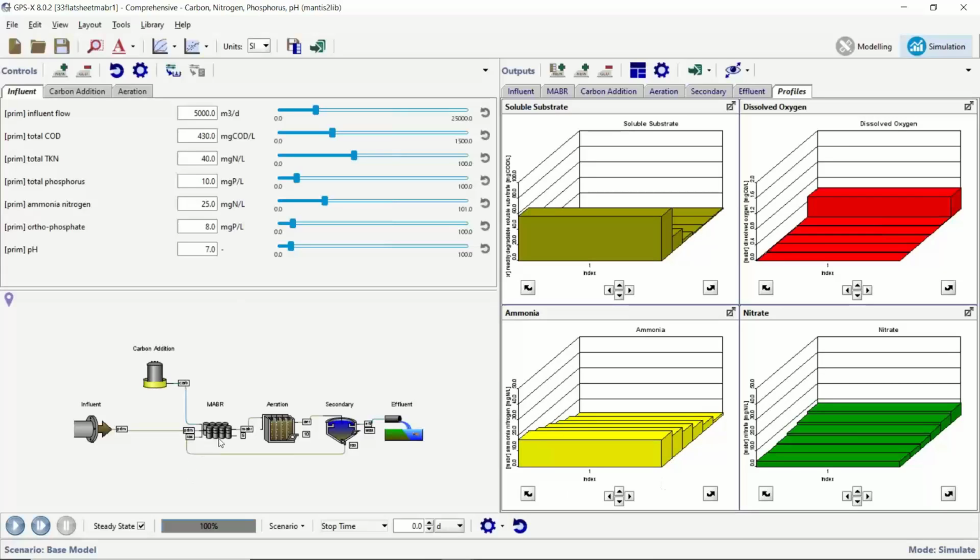And this is going down. Now, as I mentioned, these units are sort of fitted together in parallel, so that's why we're really treating them as one giant continuous biofilm surface. So we're only showing one here. But as I said, the model is totally set up to be able to create multiple units in series if that is what you're using, and that's what you like to do. We can combine them all into one GPSX unit, or you can even drop two of these on the screen and do it that way. But I like to be able to fit them all into one graph via this method here.